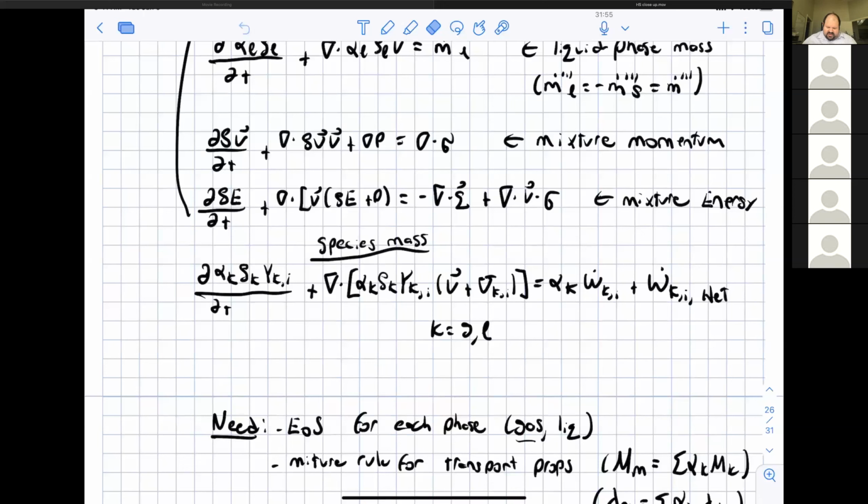Because in combustion, there's kind of a myth going around that Lagrangian methods for particles are always more accurate than an Eulerian method, but that's not true. There are some really subtle things that you need to worry about. But if you have the type of flow where a Lagrangian method is superior, it is by far superior. There is no comparison, and I will discuss those pros and cons later on.